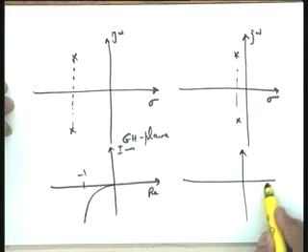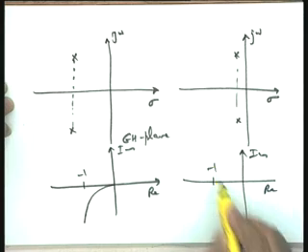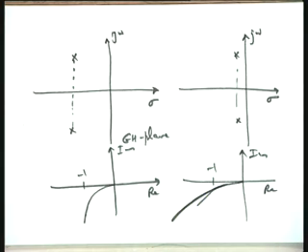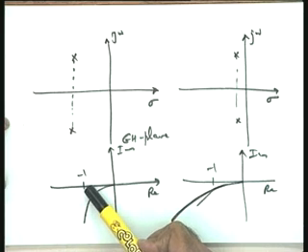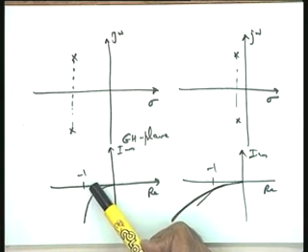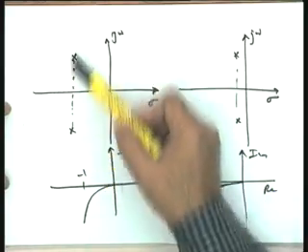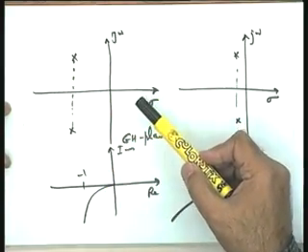case, I expect, this is real, this is imaginary, this is your -1 point, the plot will be of this nature. What is the difference between the two? How do I evaluate which system is better? You please see that the enclosure of the -1 point by the Nyquist plot is the index of absolute stability. Now, you can intuitively feel that the closer this plot is to the -1 point, the more is the risk of the system going towards instability, as is the case over here. That is, here the index was the distance with respect to the imaginary axis.